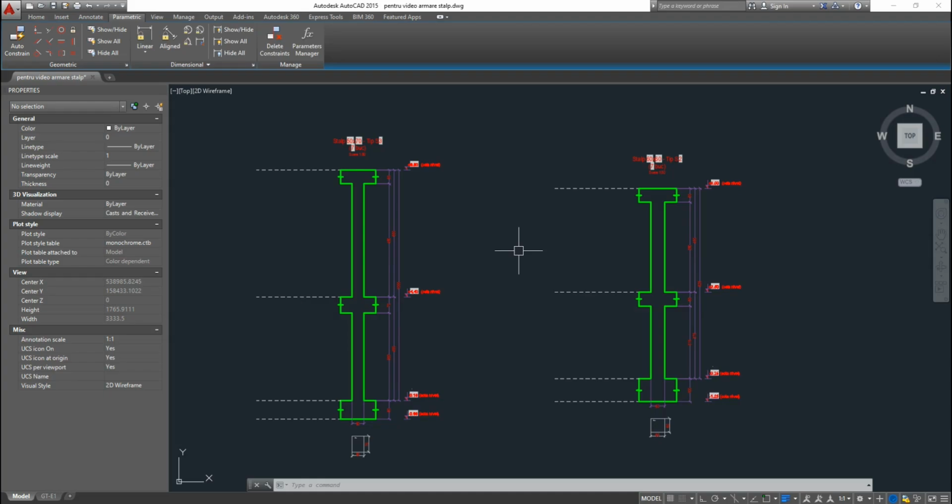We will use our first Lisp, namely the one that will construct the body of stirrups on this column. We'll dive in far more complicated constructed blocks, but with the same basic principles, using a lot of linear parameters with a lot of stretch or move actions.